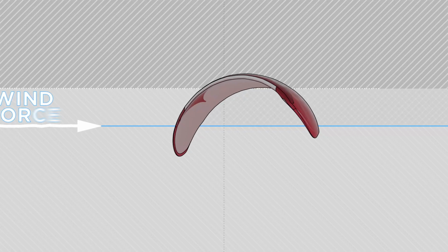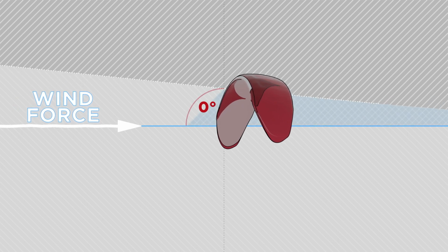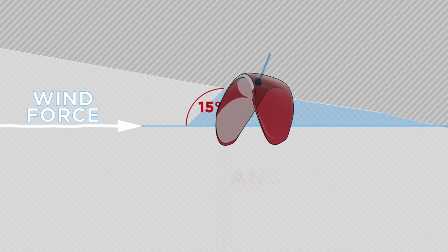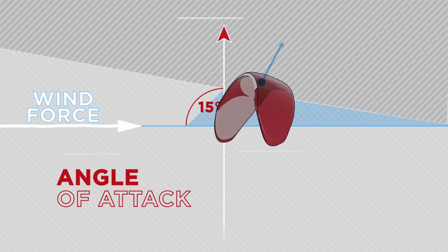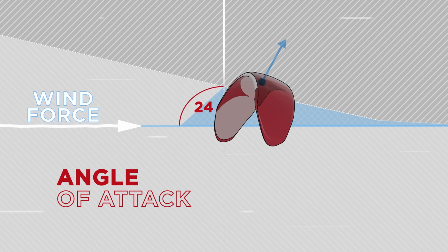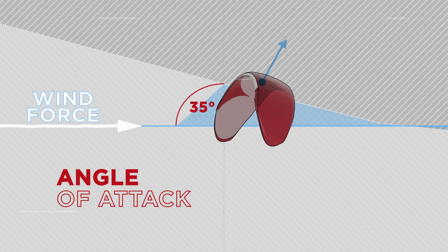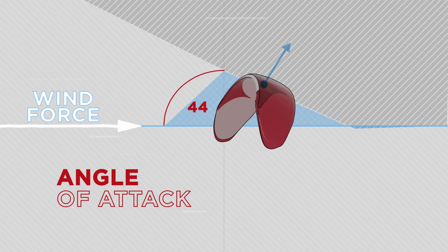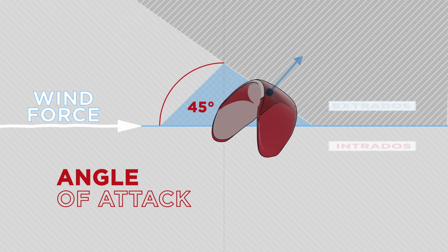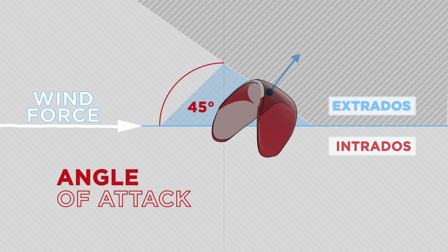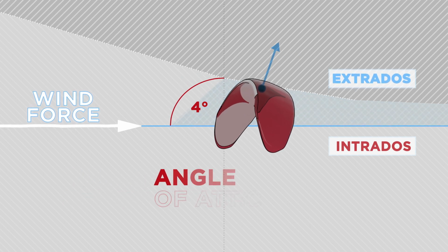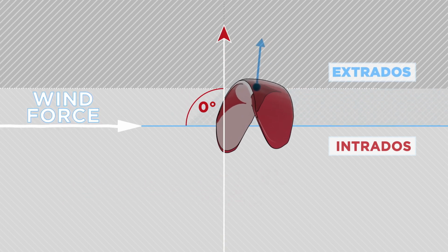Between the direction of the wind and the chord line of the paraglider wing. Okay? And this angle is called the angle of attack. When the angle of attack is small, then the pressure underneath of the wing is much larger than the pressure on the upper surface of the canopy. That's how the paraglider wing makes lift force. Okay? The theory is very simple.